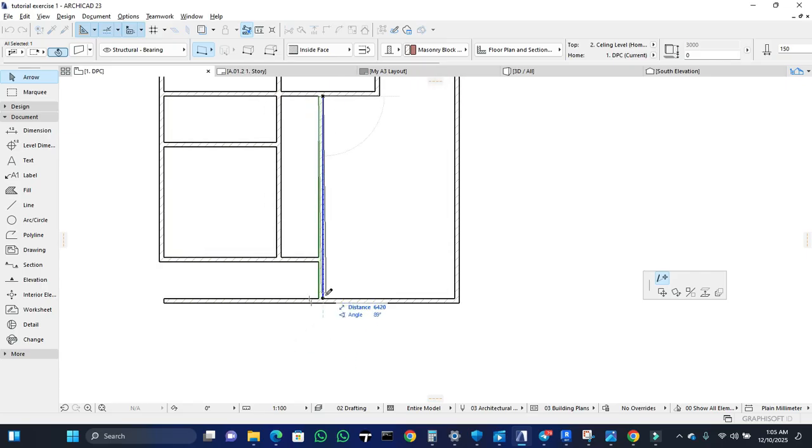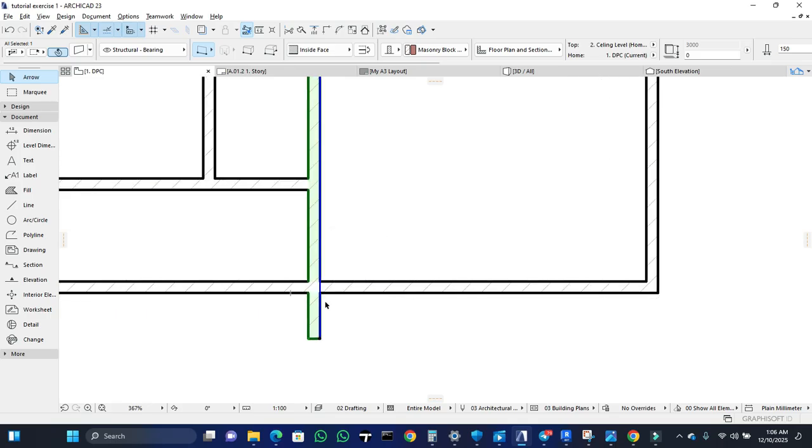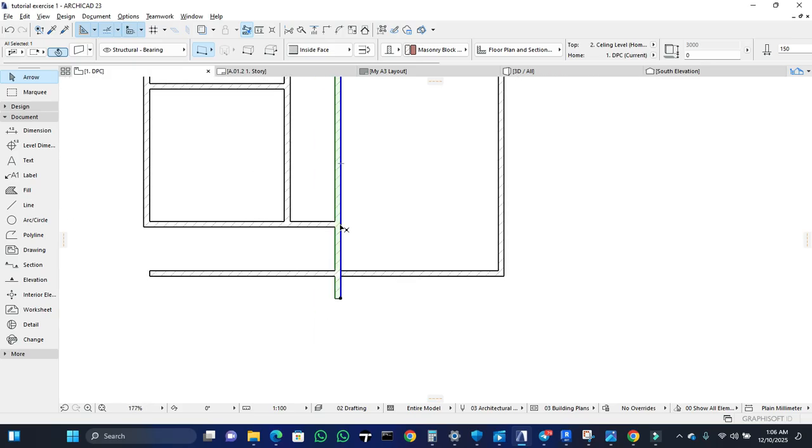So now let's say the whole of here is our veranda. So let's close up this point. You select the two perpendicular walls and click on intersect. You now have a simple plan. Let's check if this can accommodate the dining comfortably. So measure tool, click on the first point, click on the second point. This is 2.4, which could work, but I'd rather give that 2.4 to the kitchen than the dining.